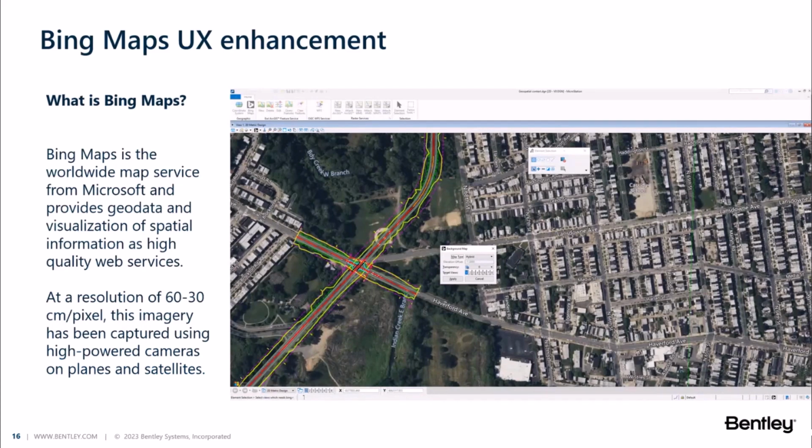How do you locate your project in real coordinates, Simon? Okay, so we would start with a site survey of some description, and we would look to set up some sort of survey control network, and we would understand what the geographical coordinate system needs to be.